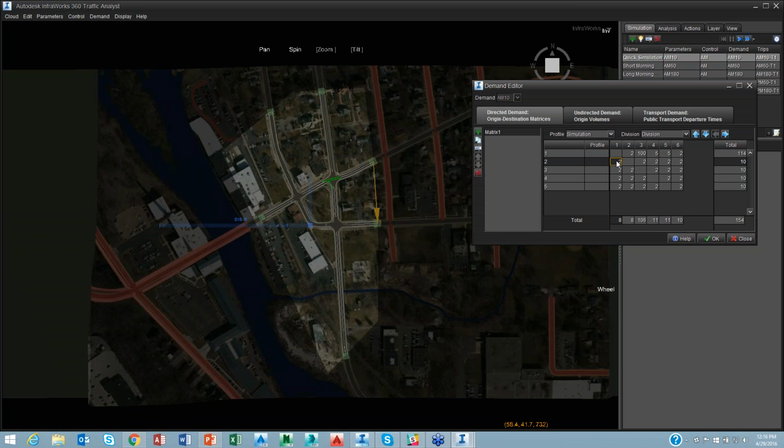All right, let's do the same thing for the other ones. Now in this case, because that's a one-way street like we talked about before, I'll have no traffic coming out of any of those areas. So I'm going to set those all to 0 because traffic will only go the opposite direction. Nothing will come out of that zone.